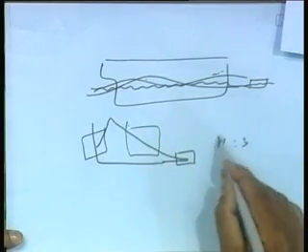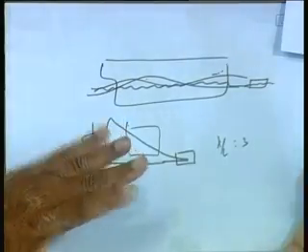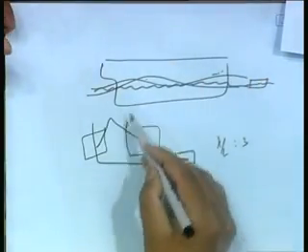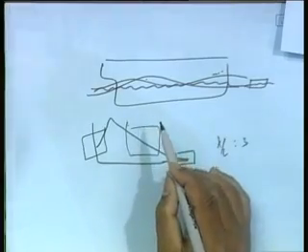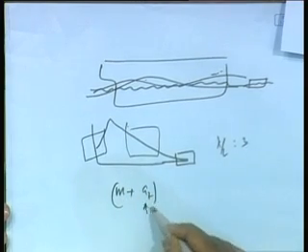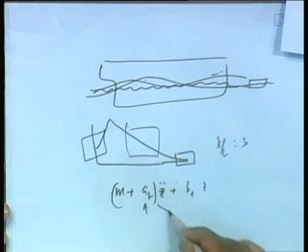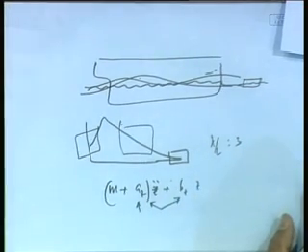If L is 300 meter, lambda is 900 meter, but most lambdas in open ocean are 300, 400 meter itself. So, I end up getting lambda by L to be around 0.75, 1.5 type, and in such cases I have inertia domination. So, my point of saying is that for large ocean going waves, you cannot avoid studying dynamics, and in order to get dynamics I now have this problem of having to estimate the dynamic part, which I have to estimate to some moderately acceptable degree.